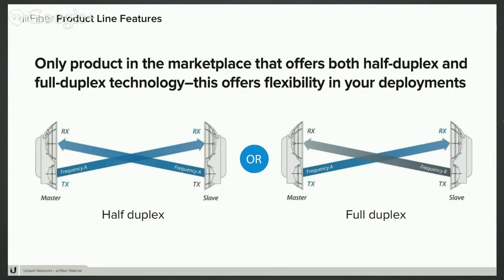And what that is, in a full duplex link, you can set one direction to utilize a lot of bandwidth, say a 50 megahertz or 40 megahertz channel, where you have a lot of data to push in one direction. But on the channel coming back, you may not have as much data. And so for that channel, you can set it up to use, say, 10 megahertz of spectrum, making the AirFiber a very spectrally efficient radio as well.